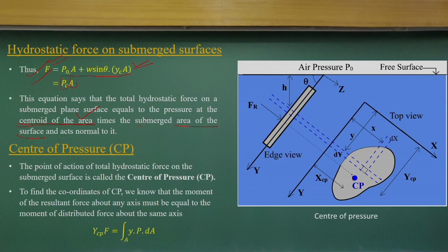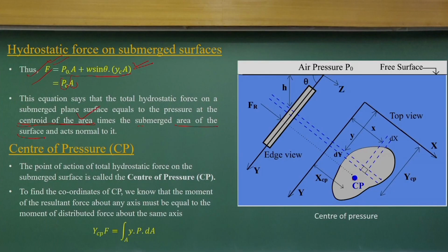But remember that this is not a single liquid case; for this case we have a single liquid system, which is easy to do. But if you have a plate submerged across two liquid interfaces, in that case you have to do the integrations to find where it acts.